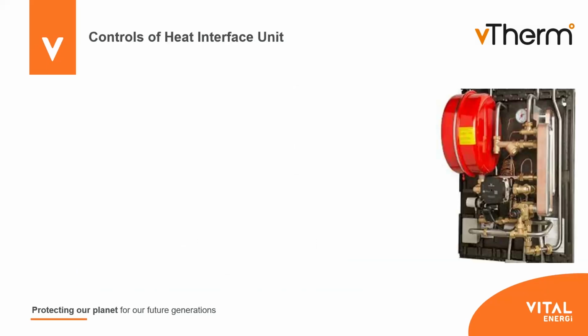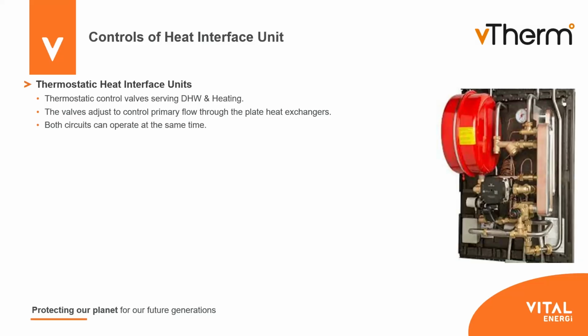So, how do we control HIUs? What do HIUs or heat interface units look like? So originally we had, as I've mentioned, the thermostatic heat interface unit, and therefore they would have had control valves. And as you can see, those valves would have had a capillary going to some form of head, and that would then dictate the temperature that it would control at.